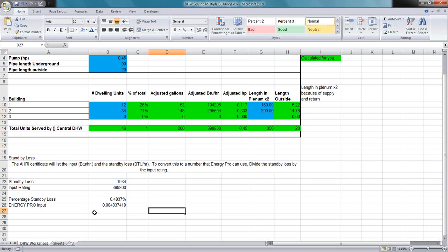Next question: what should we do when the equipment, whatever the equipment is, water heater, pumps, tank, boiler, has no nameplate or the manufacturer is no longer in business? This goes back to the default table, vintage table issue. Take a look in our handbook. Feel free to ask us. Google is your friend. Go ahead and search Title 24 vintage table, Title 24 default values, and you will find some guidance on what we use for these numbers, and just base it off of the best professional judgment that you can get on when that system was installed.